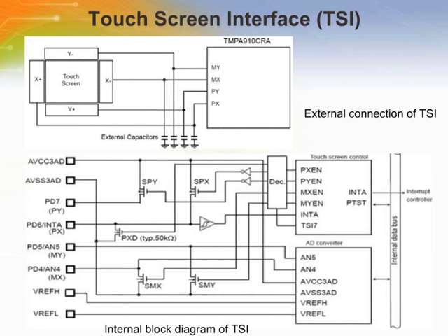An interface for 4-terminal resistor network touchscreen is built in. The TSI easily supports two procedures: touch detection and XY position measurement. Each procedure is performed by setting the TSI control register, TSI CR0 and TSI CR1, and using an internal A to D converter.